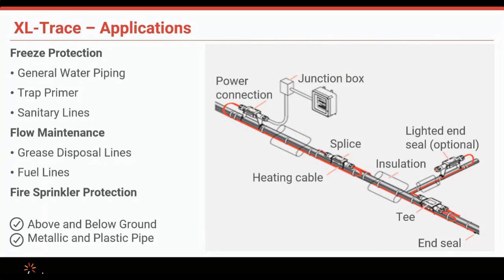Flow maintenance. So anytime you're looking at maintaining a higher temperature, greasy waste is an example, we like to design and maintain for 110 degrees versus freeze protection, which would just be at 40. So that makes a big difference on how many watts per foot is required.